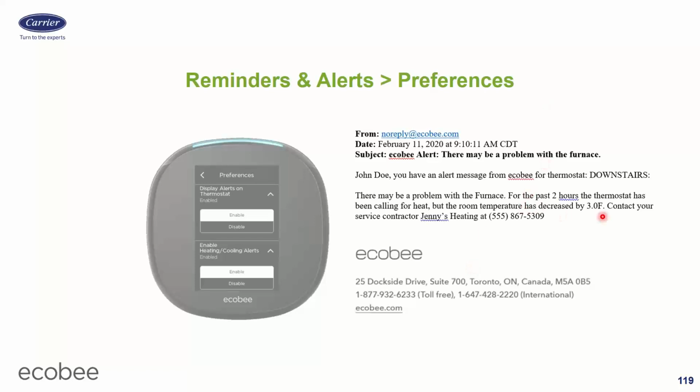This is that one I was telling you about. So this one that said, hey, for the past 2 hours, we've been calling for heat, and the temperature went down 3 degrees. There's not any fixed number on this. Sometimes I'll see them where it's 3 hours, sometimes 4 hours, but it's usually either a short amount of time with a big temperature drop, or it's a long amount of time with a little bit of temperature drop happening, or no temperature increase, or mild temperature increase. So kind of trying to gauge the problem there. It's a proprietary thing. You just turn it on or off. You don't get to say how it works.